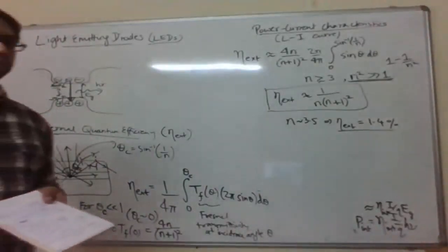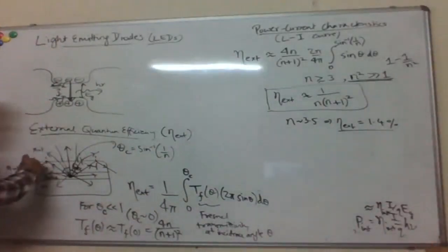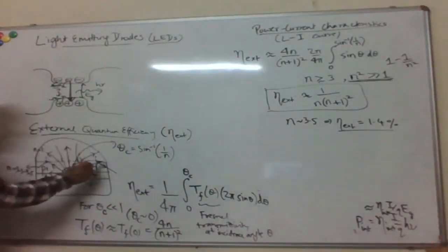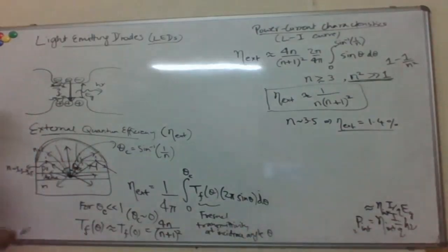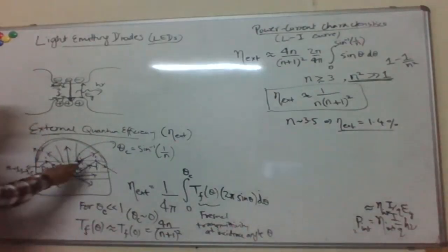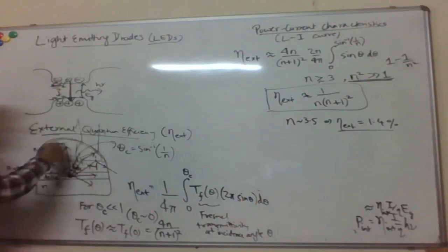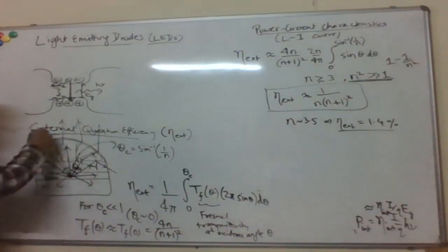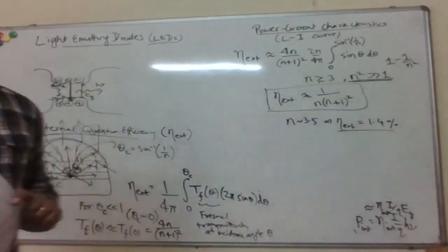So in some cases, certain things are done to improve the light collection. Sometimes some lens kind of structure is made on top here, like a glass dome, so first of all you decrease the index contrast, right? So that the critical angle becomes larger, and then this lens design also collimates the light coming out into a particular direction.